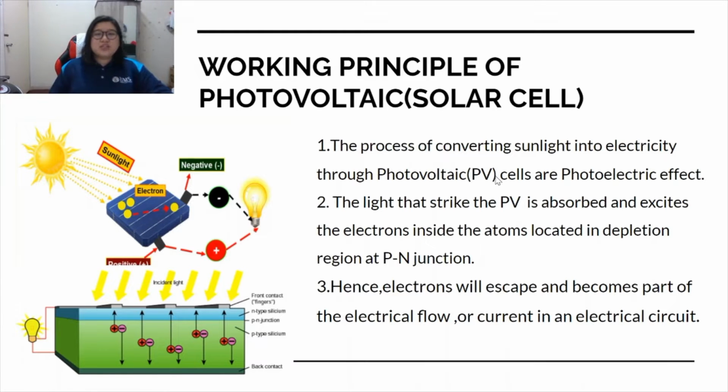So this p-n junction is due to the p-type layer that attracts the negative charge and the n-type layer that attracts the positive charge. When these two layers combine, it will form a depletion region that consists of no positive and negative charge inside of it. It is located inside the p-n junctions and has an electric field inside of it.